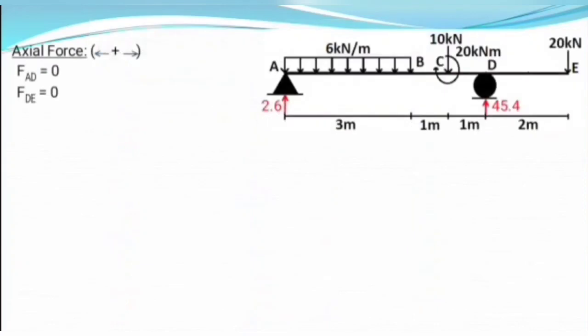Now after axial force we are going to move to shear force. First, what do we mean by shear force? Shear force is another internal force which takes account of all the transverse forces, or the forces that are acting in transverse direction with respect to the axis of the beam. If you need to plot the shear force diagram of the beam, we need to calculate shear force at each and every point of the beam.